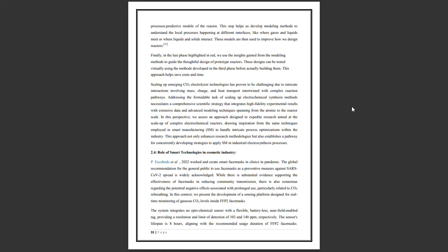In this context, we present the development of a sensing platform designed for real-time monitoring of gaseous carbon dioxide levels inside an FFP2 face mask. The system integrates an optochemical sensor with a flexible battery-less near-field enabled tag, providing a resolution and a limit of detection of 103 and 140 ppm respectively. The sensor's lifespan is 8 hours, aligning with the recommended usage duration of an FFP2 face mask.